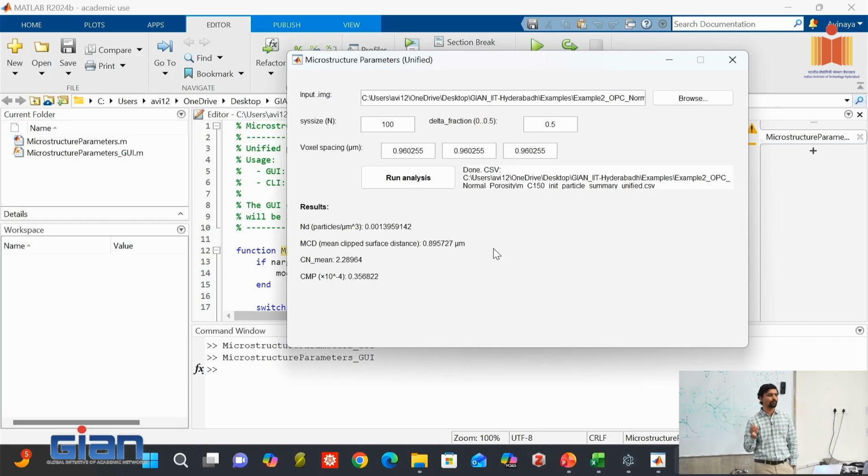It's not defined, but you can most probably assume that if you have a parameter of 1 versus a parameter of 2, the 2 is going to have higher yield stress than the 1. So those kinds of comparisons you can make, like for certain mixes, can I incorporate some kind of aggregate so that I get higher structural parameters, so that most probably I'll end up being printable plus having more yield stress. Those are the kinds of things we can play around with.